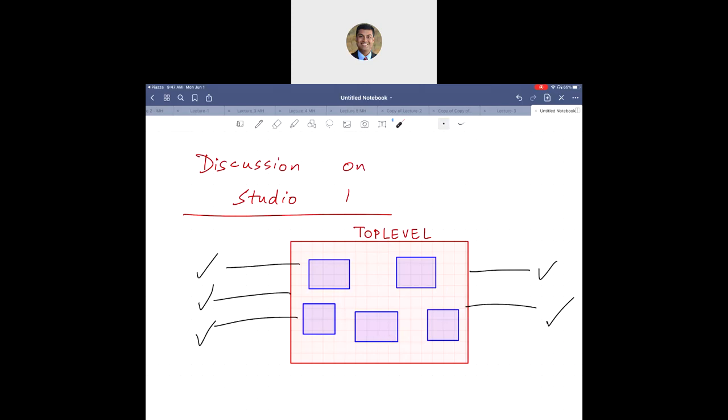In this case, we are showing one, two, three, four, five VHDL files, and the sixth one is the top level VHDL file, which puts the 5 of them together. But in total, there is only one XDC file which talks about the main 3 inputs and 2 outputs.